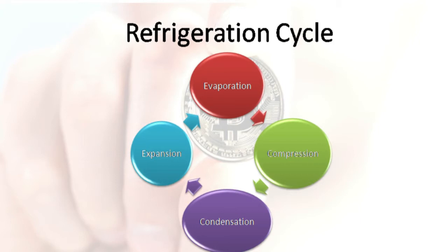Evaporation is the first phase, in which heat is derived from the return of hot air from the space where your mining rigs are. The hot air from the space is then blown through the evaporation coil. The evaporation coil has cold liquid running into it, which, by extracting the heat from the airflow through the coil, turns this liquid into gas. The conversion to gas can happen at this relatively low temperature for a state change due to the pressure being maintained within.